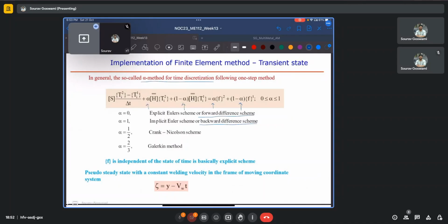Similarly here, and so on. And here, the subscripts actually refer to the discretization in the spatial domain, and the superscripts such as 1 and 2 will refer to the discretization in the temporal space. So Ti2 minus Ti1 can refer to the difference in temperature at node i between time step 2 and time step 1,